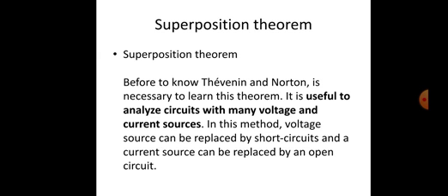However, if the linear network is operating in steady state and each external independent source has a different frequency, then superposition can be applied to compute the average power or active power. If at least two independent sources have the same frequency, for example in a power system where many generators operate at 50 Hz to 60 Hz, then superposition cannot be used to determine average power.